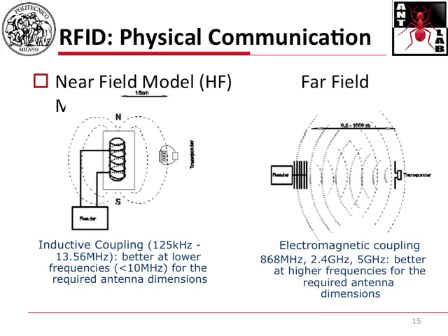So, just to be very synthetic, the idea is the reader generates a magnetic field, and this magnetic field excites the coil, which is at the receiver side of the tag, and which generates a current in the coil itself, which is then connected to the backend RF system.